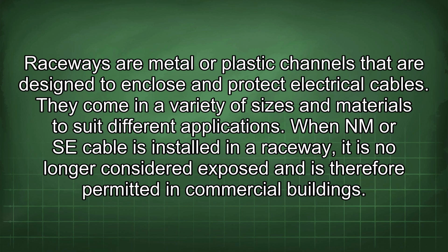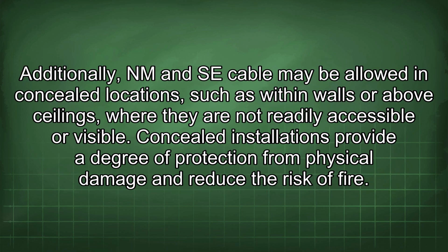When NM or SE cable is installed in a raceway, it is no longer considered exposed and is therefore permitted in commercial buildings. Additionally, NM and SE cable may be allowed in concealed locations such as within walls or above ceilings, where they are not readily accessible or visible.